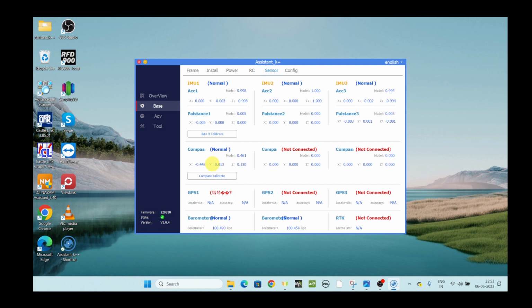Next, magnetic compass calibration. For compass calibration, we should rotate horizontally in the clockwise direction and then vertically in the clockwise direction in order to complete the compass calibration. For example, when the flying field changes, the magnetic compass calibration needs to be done again. It should be recalibrated. Before calibration, please check if there is strong magnetic interference nearby.